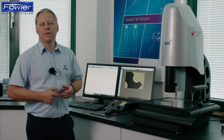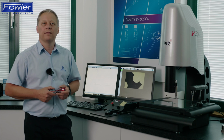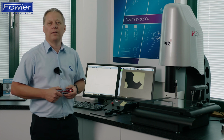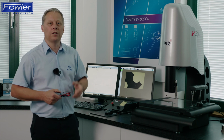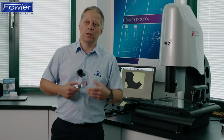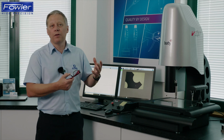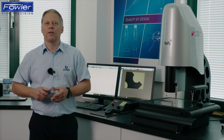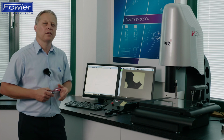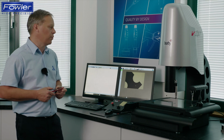Okay, so in this video we've covered how easily and quickly we can create vision programs and touch probe programs. We've asked the software to decide what features are. We can group features together and the software makes a decision about which tools to use and what the features actually are. We've repositioned programs by simply dragging the program over or visually aligning it. So we're taking away the need to measure reference features and making the user interface a far simpler process.